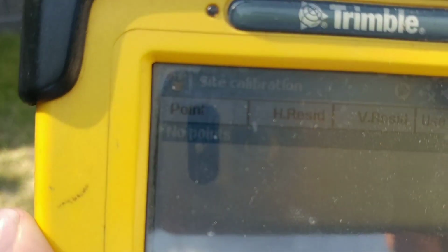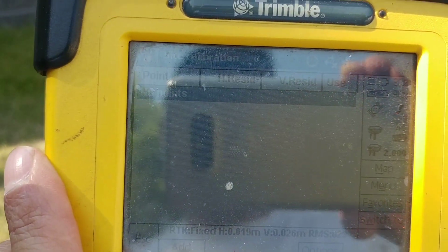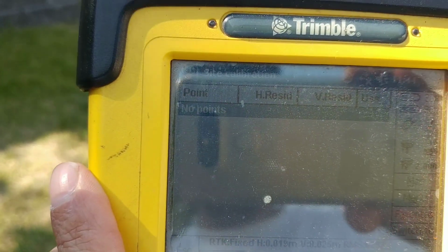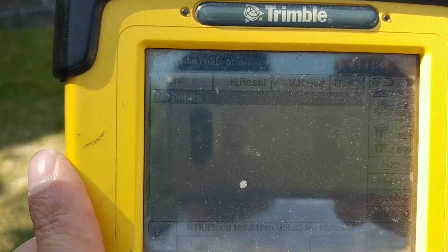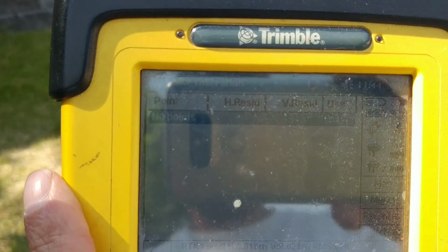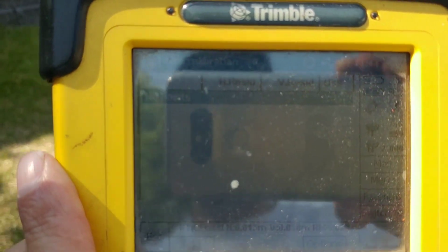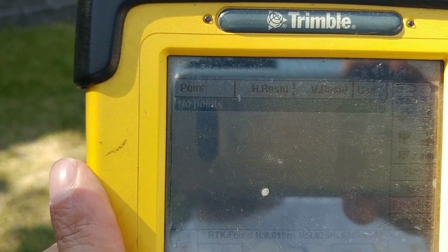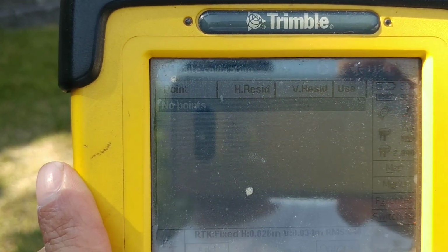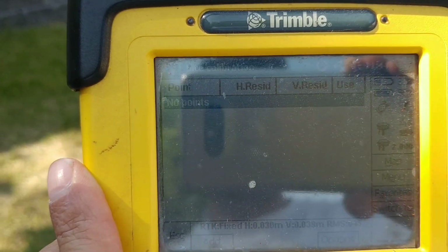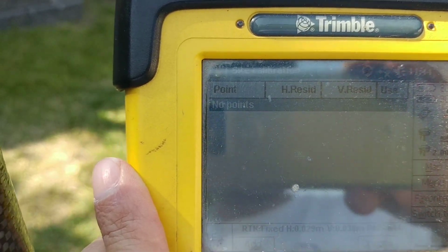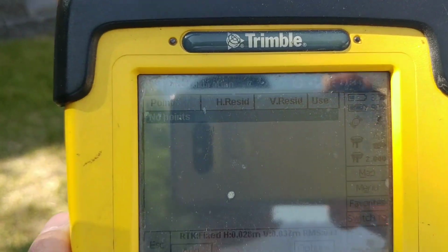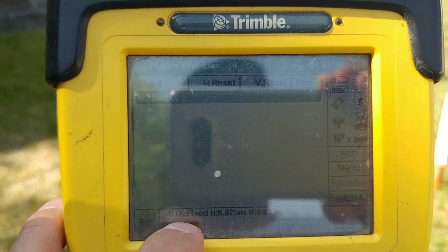What you would normally do is have a coordinate file uploaded into the data collector with your points. You go measure one of those points and say you survey it and call it point 100, and your point 100 is actually, say, 0.53 in your total station job. So you match the points right here, and you go add right there.